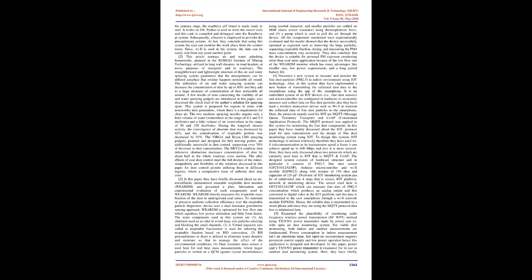accurately measure and collect data on fine dust particles. Also, they have used a wireless transceiver device such as Wi-Fi to transmit the collected data of fine dust particles to the smartphone. Here, the protocols mainly used for IoT are MQTT, Message Queue Telemetry Transport, and CoAP, Constrained Application Protocol. The MQTT protocol was applied to this system for monitoring the fine dust components.